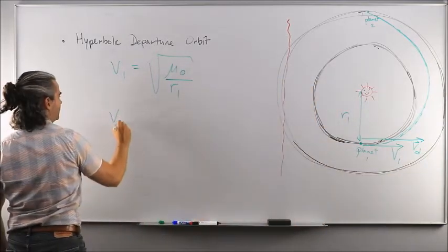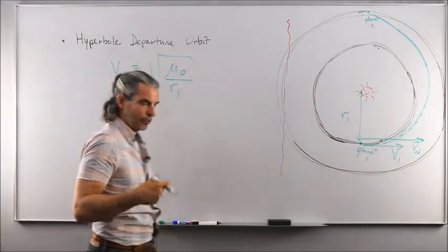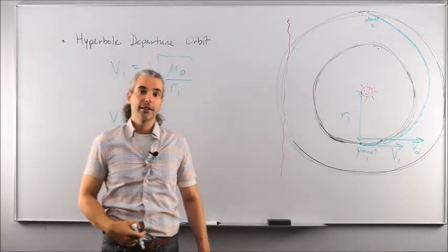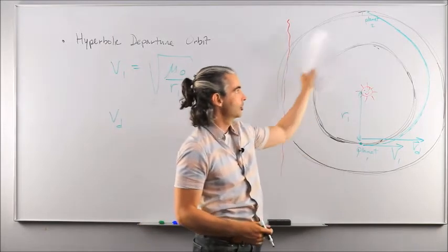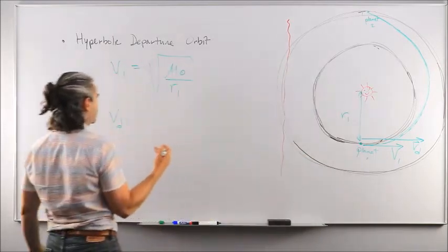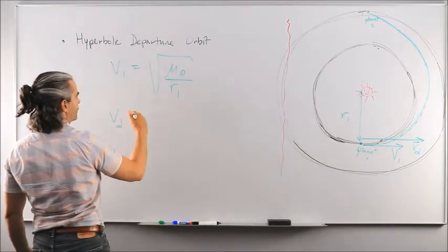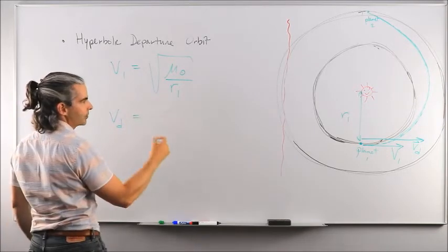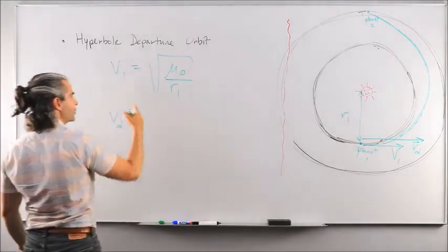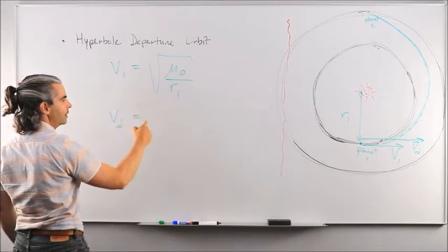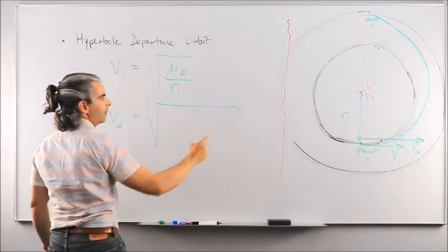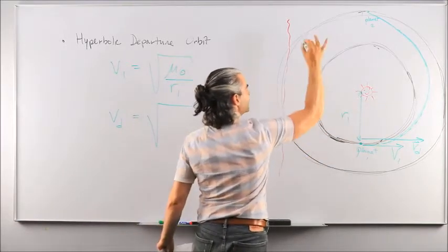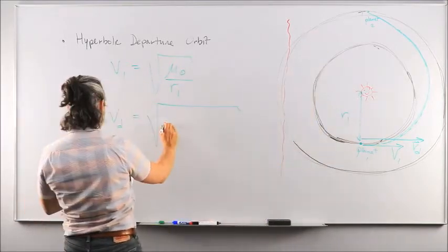All right, so this is the same as the first few orbital maneuvers we've looked at in this chapter, where we were going from a circular orbit to a larger elliptical orbit. So this is exactly the same, even if I'm using a different nomenclature for the variables, but that's the same idea. So VD is going to be larger than V1, and is going to be obtained by the vis-viva equation applied at the perigee of this big elliptical transfer orbit.